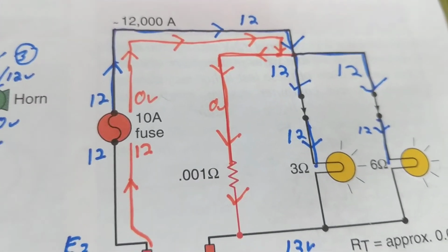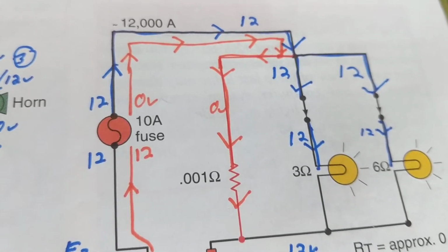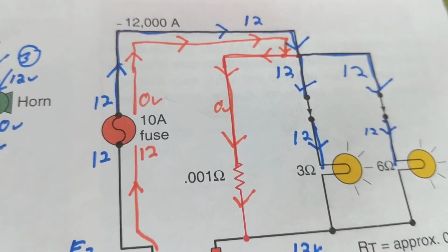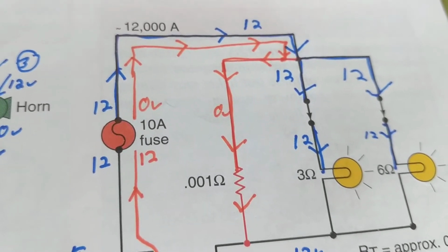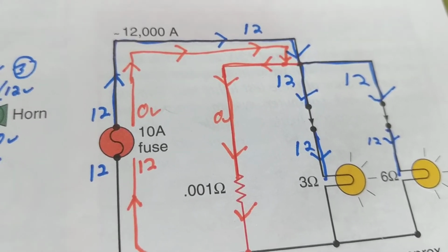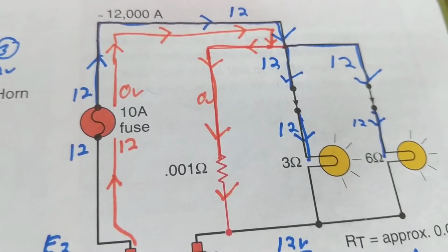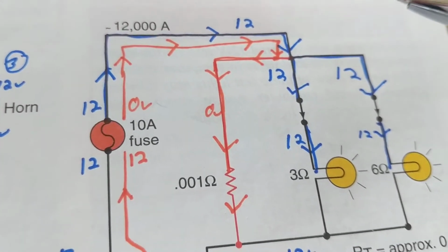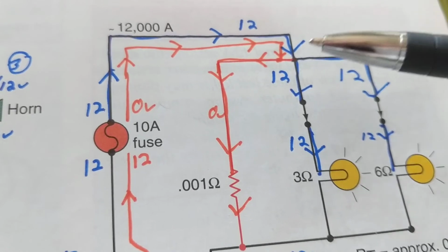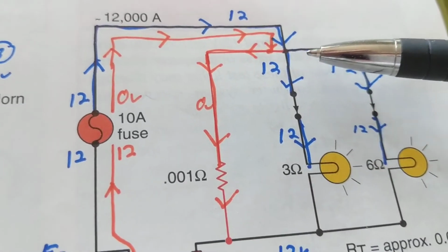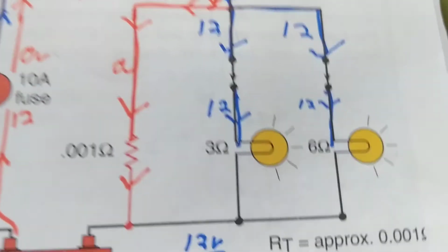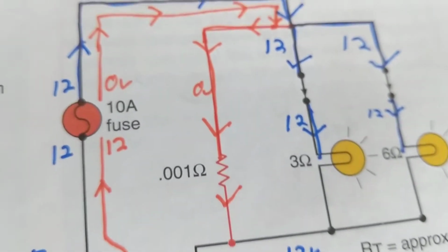Use a good voltmeter, number one, with high input impedance, because you're measuring up to 1/100th of a volt. If it's supposed to be between 0.3 and 0.4, it makes a difference if it's 0.31, 0.32, 0.34, 0.35. I'm going off topic, but I was asked this: if the throttle body is, let's say, closed at 0.5 to 1 volt, and then it opens up at 2 to 3 volts, depending on the system. Some have wide open throttle at 4.5 to 5 volts.